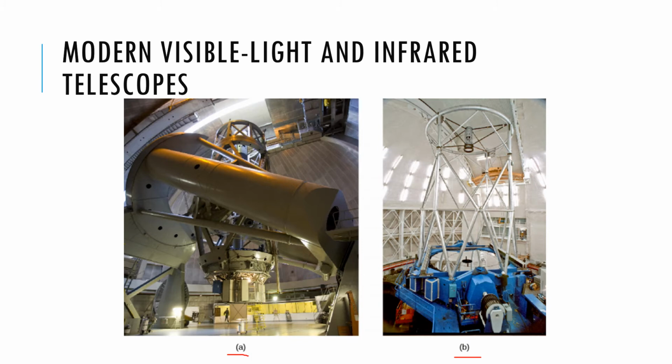The Palomar telescope is a massive steel structure designed to hold the 14.5-ton primary mirror with a 5-meter diameter. Glass tends to sag under its own weight, hence a huge steel structure is needed to hold the mirror. A mirror 8 meters in diameter, the size of the Gemini North telescope, if it were built using the same technology as the Palomar telescope, would have to weigh at least 8 times as much and would require an enormous steel structure to support it.